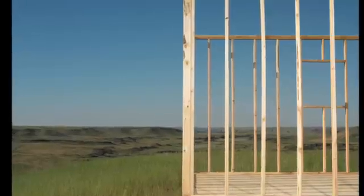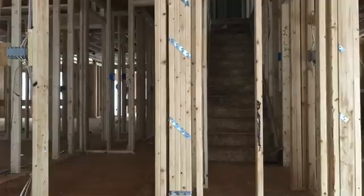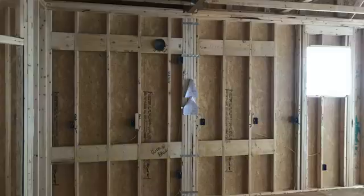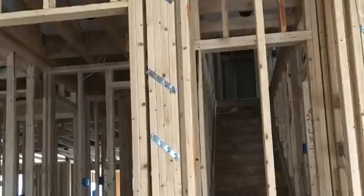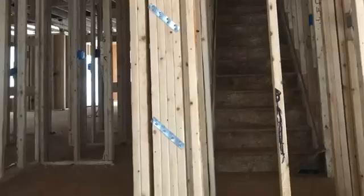Studs can stand individually, spaced out either 16 or 24 inches center to center, or they can be fastened together in groups known as stud packs. These packs sort of act as makeshift columns in our walls. They carry heavy point loads from somewhere above and transfer that weight down to a safe point below. But studs never actually touch the subfloor.